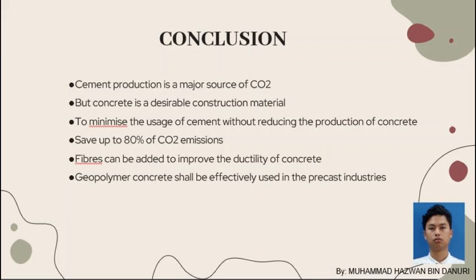Like OPC concrete, geopolymer concrete has a brittle failure. Alternatively, fibers can be added to improve the ductility of concrete. The properties of geopolymer include high early strength, low shrinkage, freeze-thaw resistance, sulfate resistance, and corrosion resistance. These high alkali binders do not generate any alkali aggregate reaction.